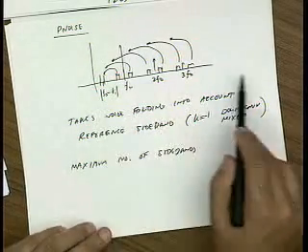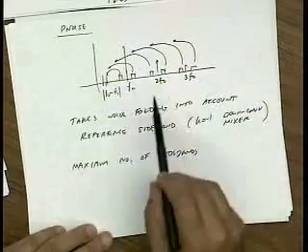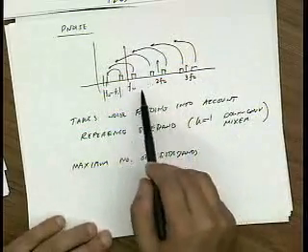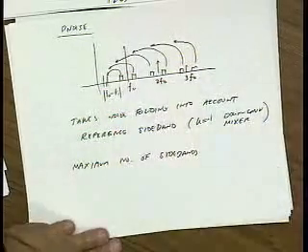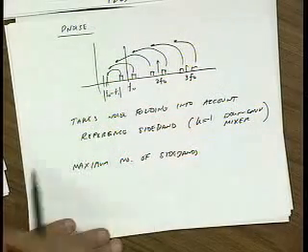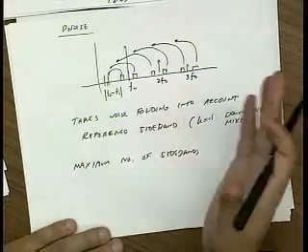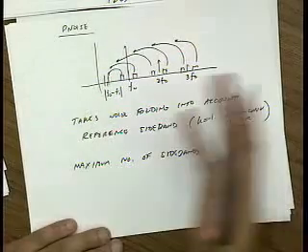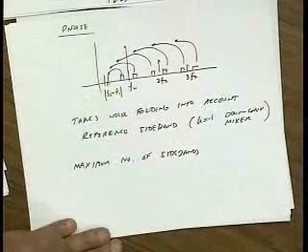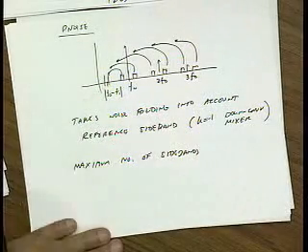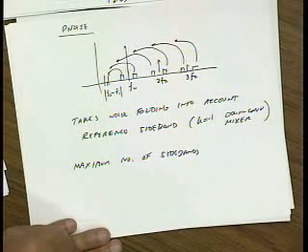Because obviously it can't do an infinite number. It would take an infinite amount of time. So what it does is you tell it, take 50 sidebands into consideration, right? Usually that's pretty good. But depending, the more sidebands you specify, the longer it takes to do the noise calculation. But you basically pick enough sidebands until the answer doesn't change, right?